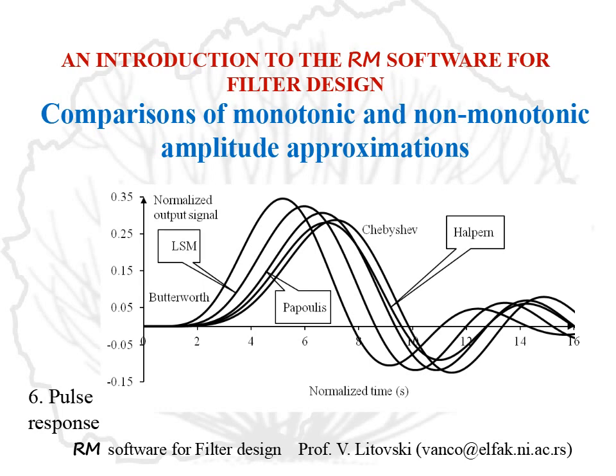Similarly, when we look at the Dirac or pulse response, we find that the Butterworth filter has the smallest delay and the largest main lobe, which is preferable for time domain applications, while the Chebyshev filter, on the other end of quality, has the second smallest lobe and the largest undershoot of all counterparts.